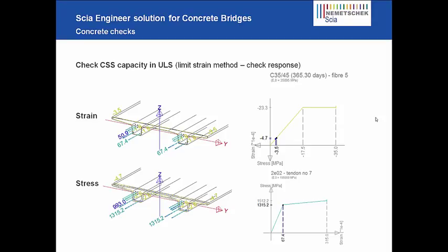So when you are checking the capacity, or you are checking the amount of reinforcement required, it will check it based on the cross section with the reinforcement in it, or the post-tensioned cables or pre-tensioned cables in it. So it will combine the rigidity of the section and the pre-stressed elements in it to find the total stiffness of the section.